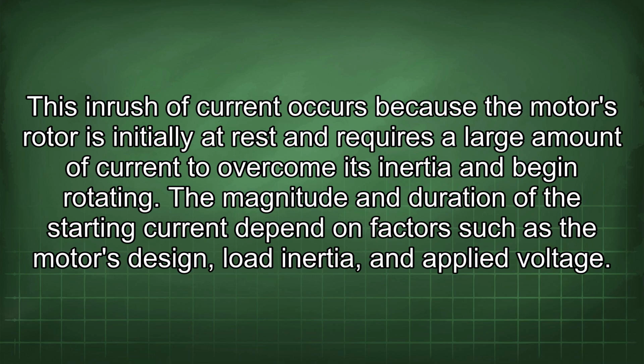The starting current of a motor is typically several times higher than its running current. This inrush of current occurs because the motor's rotor is initially at rest and requires a large amount of current to overcome its inertia and begin rotating. The magnitude and duration of the starting current depend on factors such as the motor's design, load inertia, and applied voltage.